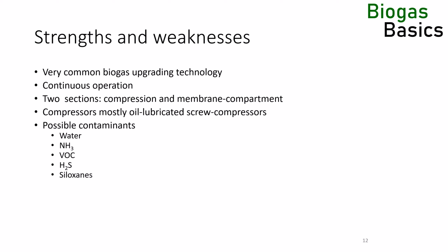Landfill plants use special temperature swing adsorption processes to capture siloxanes, but these processes require heat for the regeneration of the adsorber beds. Most AED plants will not require a designated siloxane removal step unless they feed special feedstocks. The last contaminant is carbon dust.